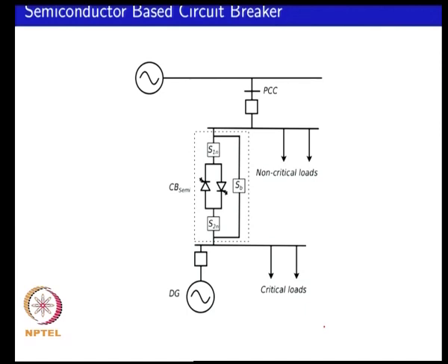What we saw is that with a semiconductor based switch, you can have faster switching, and the number of cycles can be more compared to an electromechanical switch. However, the power loss will be more, and the electrical isolation capability of a semiconductor based switch is not as high as a physical open air gap or an open gapped contact. So, electrically it is considered less rugged and it is more expensive.